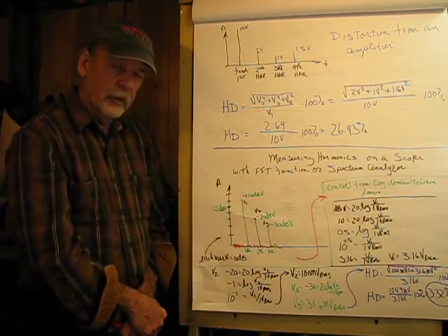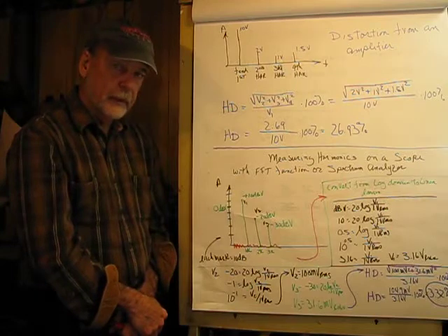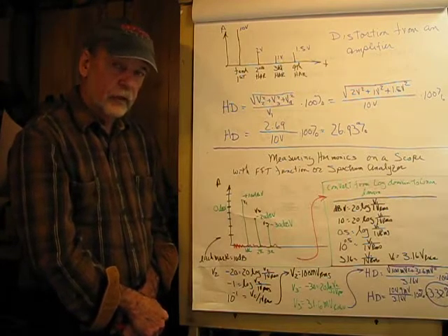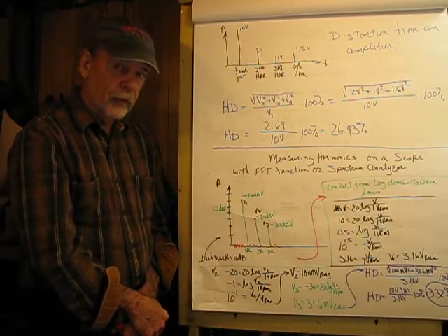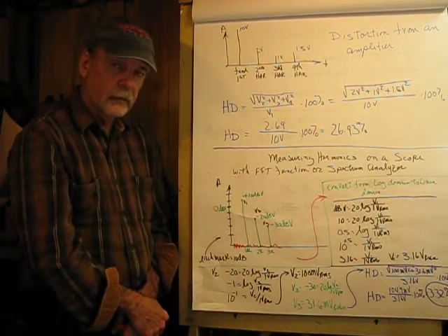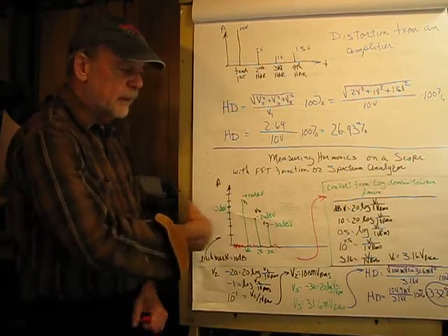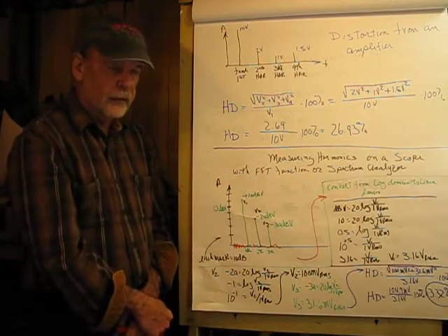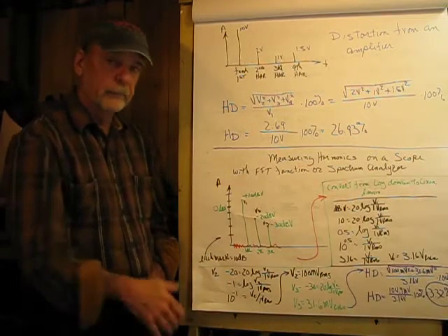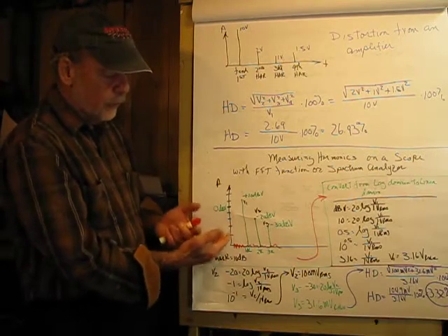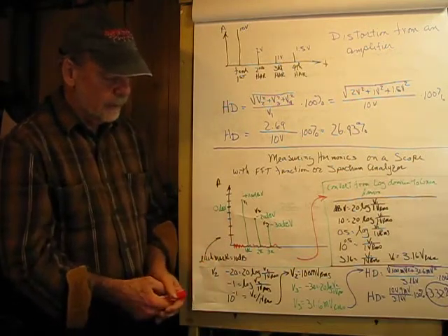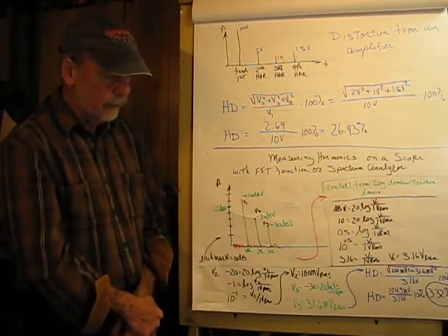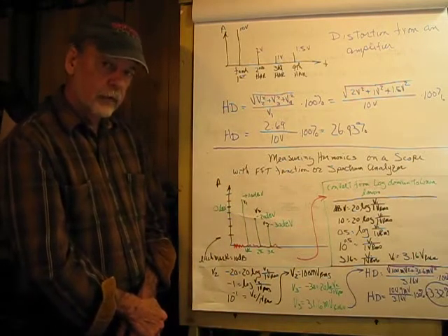Some of our simulation software is 1 volt peak. Video signals, 1 volt peak to peak. dBu, 0.775 volts RMS. So there's many different references. dBm, 1 milliwatt. So you have to be familiar with the equipment you're using to accurately measure this. But fortunately, converting this from the log domain into the linear domain is relatively simple.